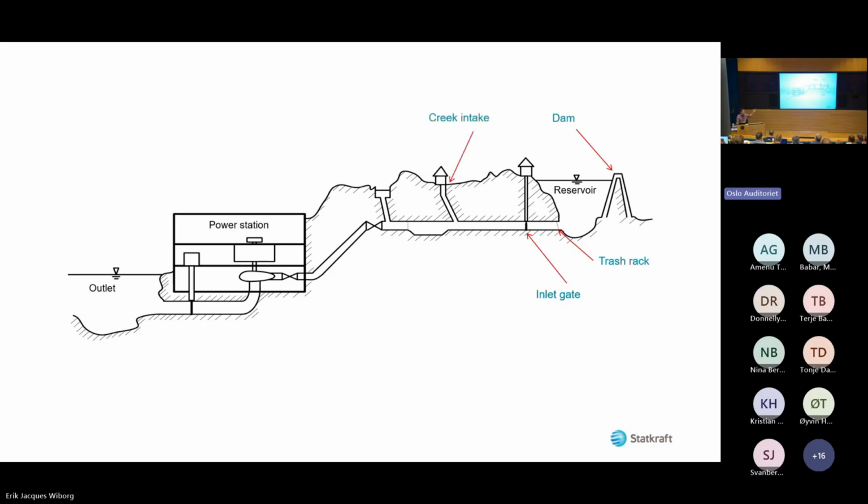Creek intakes are to get water up from the mountains that are just laying there and not being useful. So we'll just funnel the water into our system. We have sand traps in the big tunnel systems because it's going to bring a lot of sediments. The sand traps are like big caves in the tunnel system where the water goes really slow, so the sediments can fall down. New trash rack, pipe rupture valve so that we can stop the water if something happens.